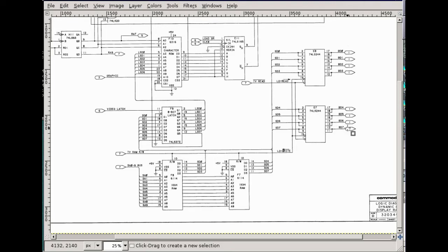So the CPU is outputting a data byte that is copied on this side of the transceivers, and is written to the RAMs. So this signal write also goes to the two video RAMs, and enables a write cycle to these RAMs.